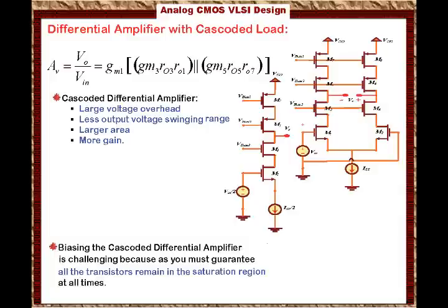This particular circuit is a little bit tricky to design because in the real world you also have to deal with the variation of the process parameters, how much VDD changes. As VDD changes, all these transistors have to remain in saturation. Also, how much the W/L changes due to the variation in the manufacturing parameters. As these variations change, you still have to make sure that all transistors remain in the saturation region, and you still want to design the circuit to give you the maximum output voltage swing at Vout, and so forth. It is a little bit challenging to design.